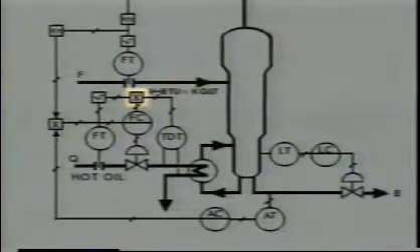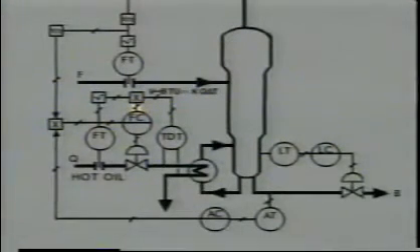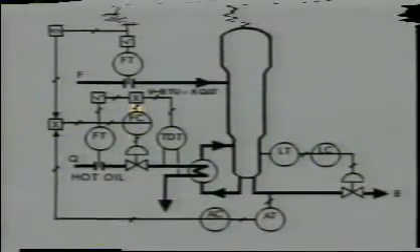But by what is it multiplied? When you trace the signal line, you see that there is a second input to the multiplying function from a differential temperature transmitter. So the linearized flow signal is multiplied by the signal representing the differential temperature. A note adjacent to the function block shows the algorithm performed by the multiplier function. After the value of the flow rate and the differential temperature are multiplied, a signal representing their product is sent to a flow controller.